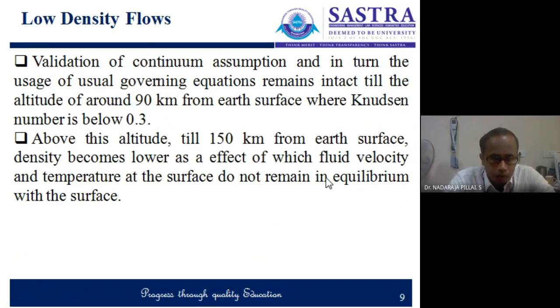Now, the validity of the continuum assumption and the usage of the basic governing equations remain intact only up to an altitude of 90 kilometers from the Earth's surface, right? Up to 90 kilometers, the Knudsen number is below 0.3.